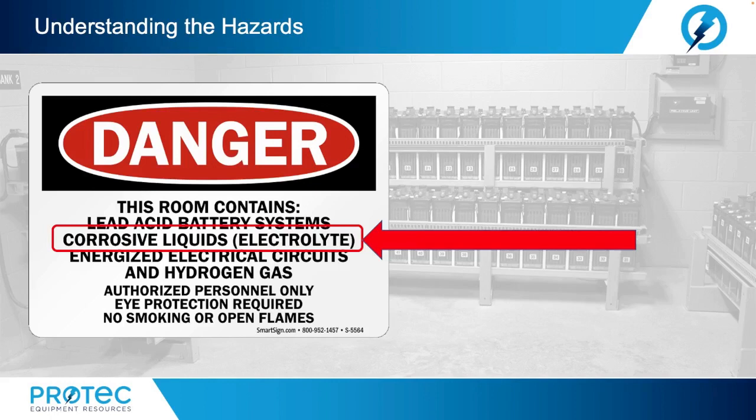When a battery is discharged, energy is removed through the reversal of these chemistry changes. When the battery is fully charged, the positive plate is lead dioxide and the negative plate is lead. The sulfuric acid is the strongest when the battery is fully charged and may be as high as 40% pure sulfuric acid,